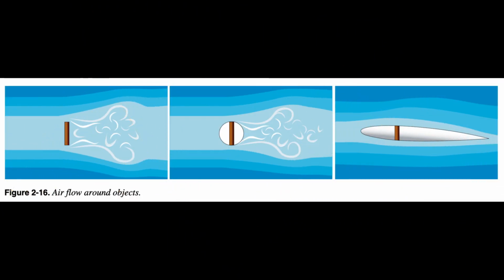The aircraft has plenty of items, area, for the wind to strike, including wing, wires, struts, pilot, carriage, engine, wheels, tubes, fuel tanks, etc. Parasitic drag can be reduced by streamlining the items. Round tubes can be streamlined, reducing the drag to 1/3, and cowlings can be used to streamline the pilot and the carriage completely, but not without the additional expense and additional weight of the streamlining.